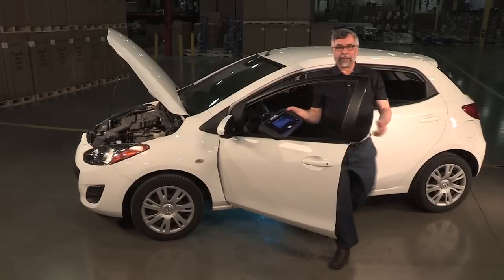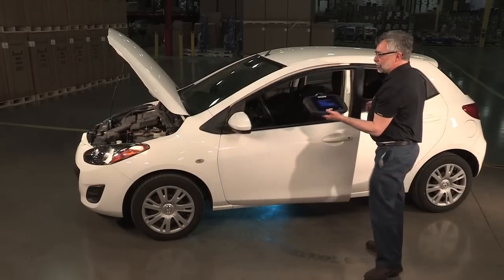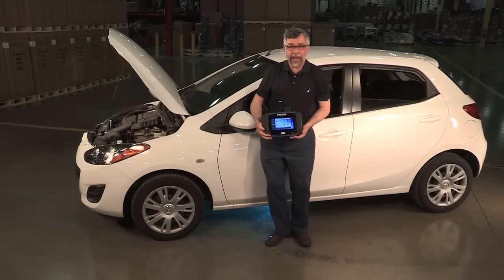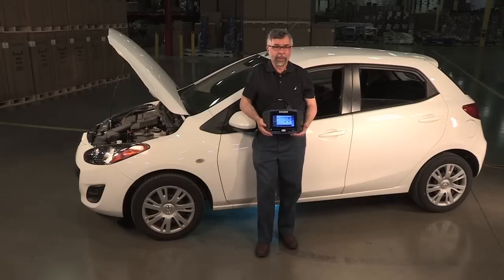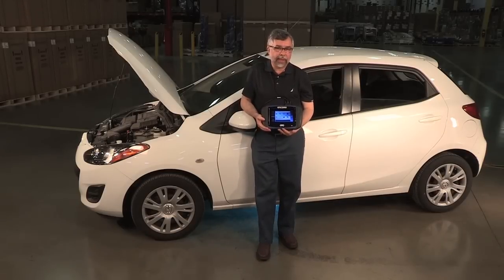What we have learned from our VE test of this 2014 Mazda 2 is that we have an intake restriction. We came to this conclusion based on the fact that we had low VE and a short-term fuel trim of 0. When we tested the mass airflow sensor to verify this, we showed at 2500 RPM that the mass airflow was reading 8 grams per second, well below spec. When we opened up the air box, we found a mouse's nest and we cleaned it out.